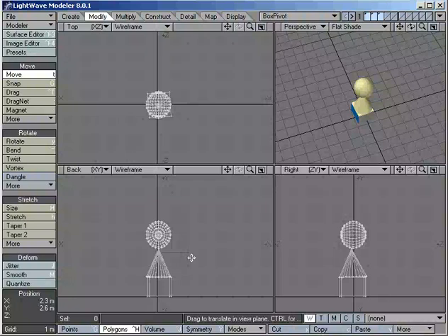You have a lot of play. I mean, you can go kilometers, you can go millimeters, or for English people, you can go miles and miles, or fractions of an inch. However, Lightwave likes things right around the one meter or the one yard scale. And I suggest that when you're building things, to keep things about that scale. Now, how do you know what scale you're in? Well, there's a couple of ways.